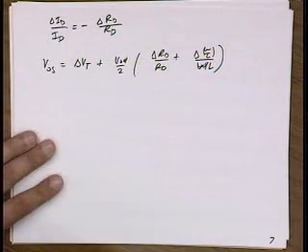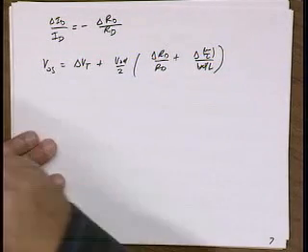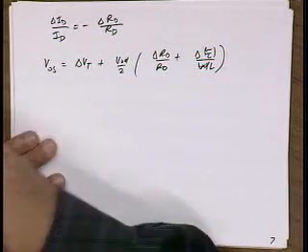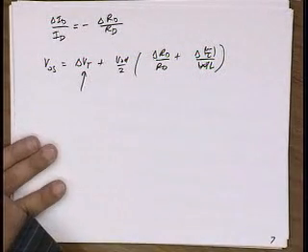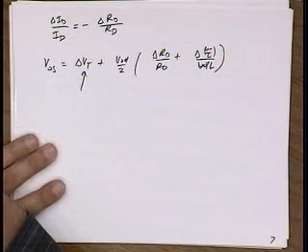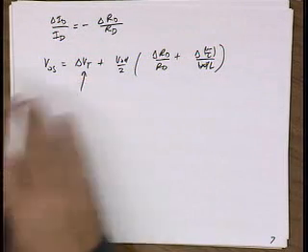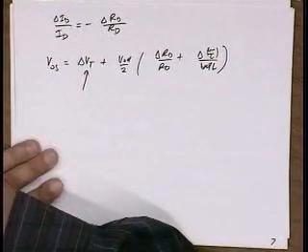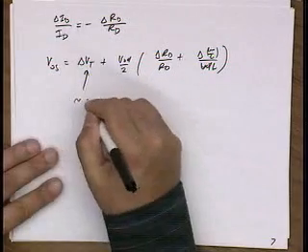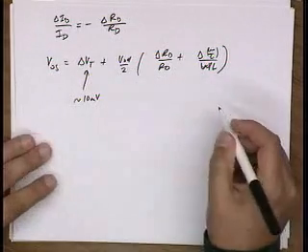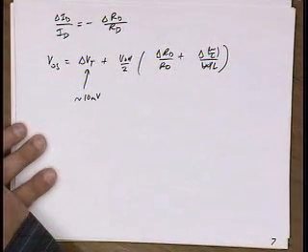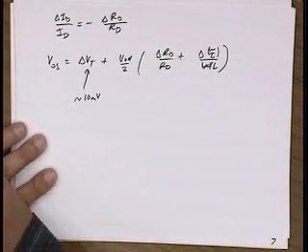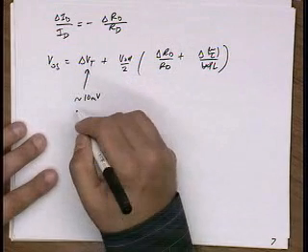Now, is this better or worse than bipolar counterpart? It's worse, right? We already said this term didn't exist for the bipolar transistor. This is actually on the order of millivolts, 10 millivolts. So it's actually a big problem. How about this term? How does this compare? Yeah, I mean, it's a very strong function of layout.